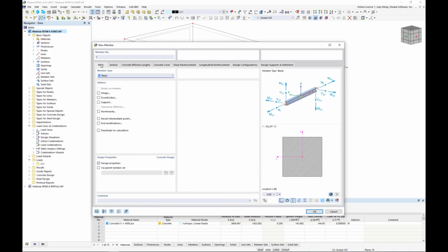Now, going back to the main tab, again, we have all of these additional tabs that are specific to the reinforcement design for the ACI standard and that concrete add-on that we have activated. I'll turn this off for now, something, again, we'll get into a little bit later, and all of those tabs now disappear. The member is considered as fully fixed when we leave everything as default here.